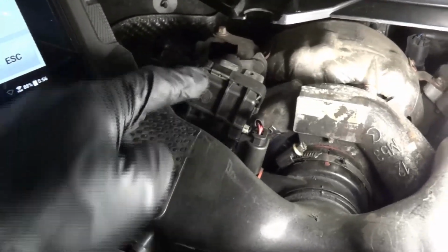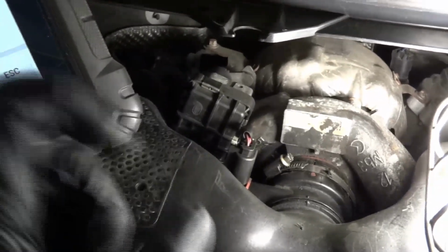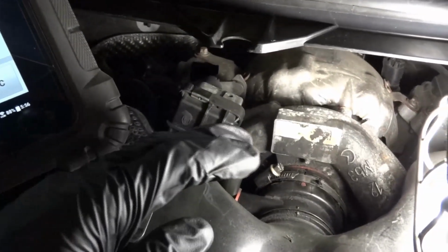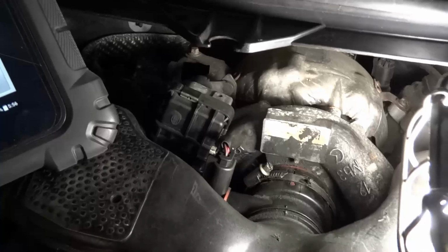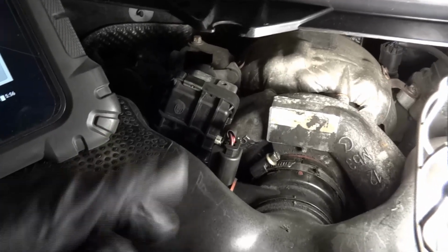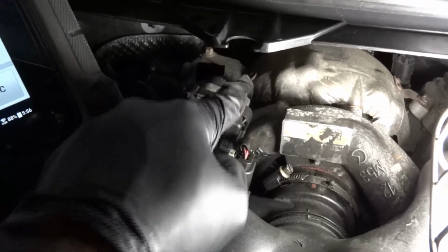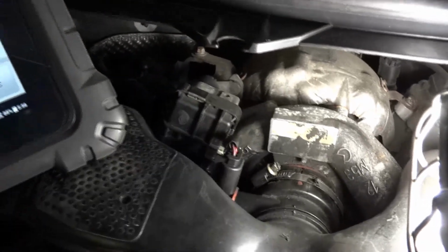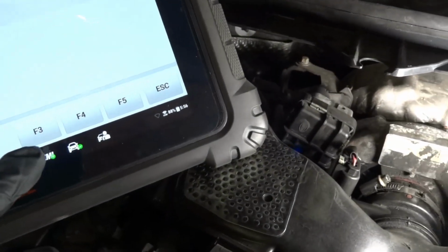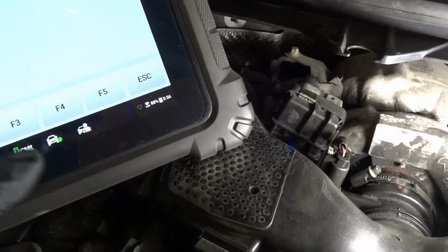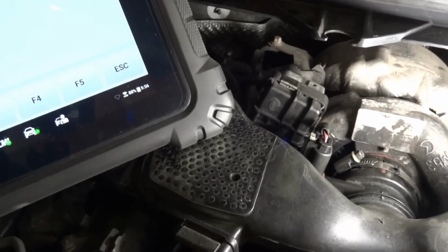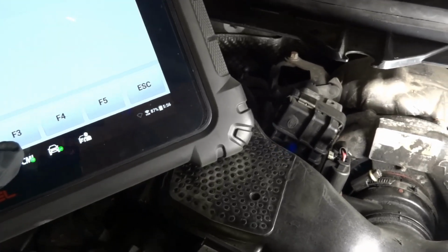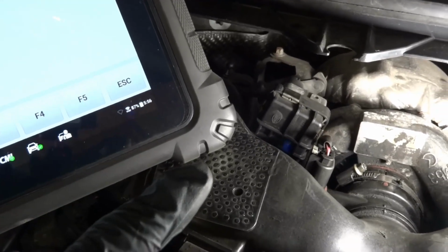So the clicking sound that you heard is the sound inside the actuator. The gears in this actuator are probably binding. And I don't think we have a problem in the turbo. I don't think the vanes in the turbo are binding, because if they were, this lever wasn't gonna go up and down as easily as it's going. So the problem is just the actuator. Let's do this once again before we try the other used actuator that I have over here. I'm gonna click on F1. You hear the noise?